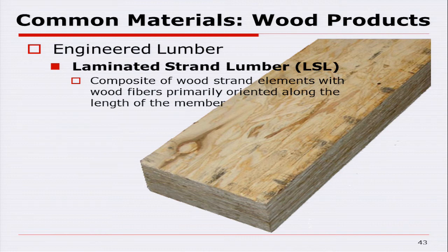We use this product, by the way, today predominantly for studs. Today, if you're making high walls and so forth, you don't want to use typical 2x4s, 2x6s, because that stuff will crook, it'll twist, it'll do all kinds of strange things on you. This stuff dimensionally is very stable, and if it's going to expand in size a little bit, it's going to be fairly uniform and expand or shrink only as it absorbs and desorbs moisture.